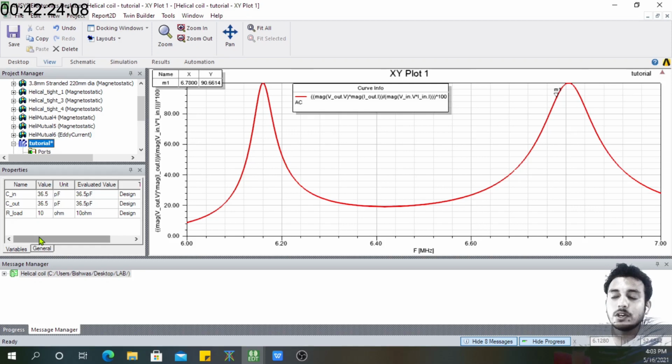So there's no point in tuning the circuit to so many decimal levels and then saying that okay, I reached 100% efficiency. That doesn't matter. So when you're working in hardware, it's about how close you can get with the hardware you have. So what is available in the market, you have to see that. It might happen sometimes that it's not always about the capacitor, because you can't change things there. So what you can change on the other hand is the inductor, right? Because you are the one who will design the inductor, right? So change the length of it, play around with the inductor's value.